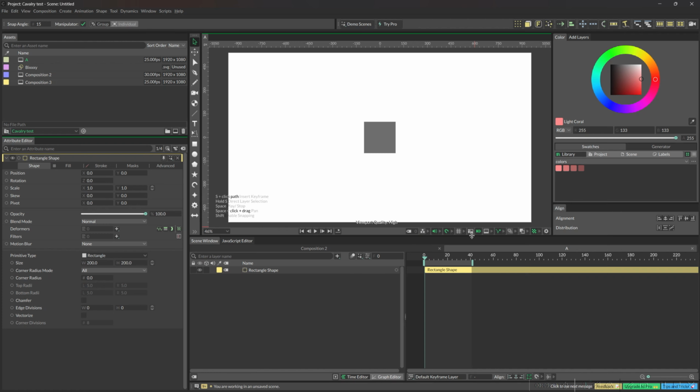Now this is playback caching. If you know anything to do with caching, once you enable it, it makes sure that it plays back in a kind of accelerated mode, which is very, very nice. So I recommend you have it enabled so it will be seen whenever you're playing an animation. Then the composition boundaries, once you click onto it, you can disable or enable composition boundaries, which is very nice. Sometimes I wouldn't love to see the composition boundaries. You can change the color and enable it by also pressing the button in there.